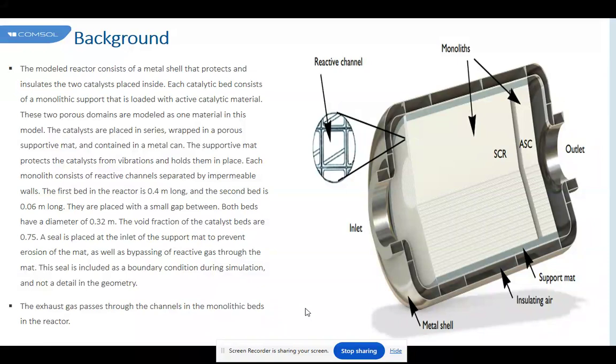First, full depletion of the CO was reached in the two substrates with a 900 per 2.5 monolith in the core. On the other hand, independent of the position, the parts of the substrate with the 400 per 6.5 monolith didn't reach 100% conversion. A 900 per 2.5 monolith has a higher geometric surface area than a 400 per 6.5 monolith.